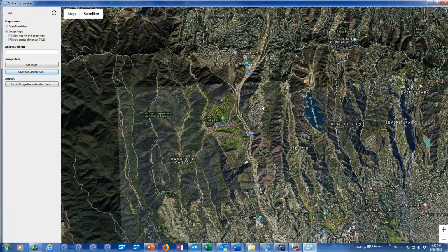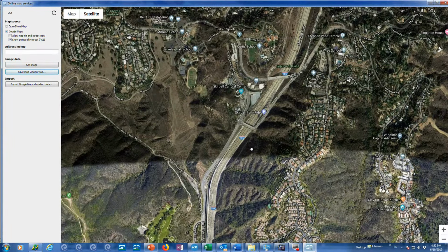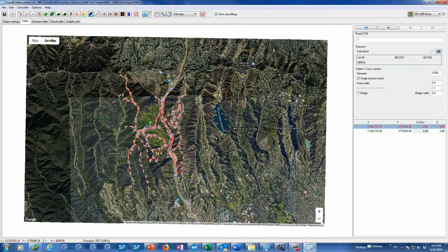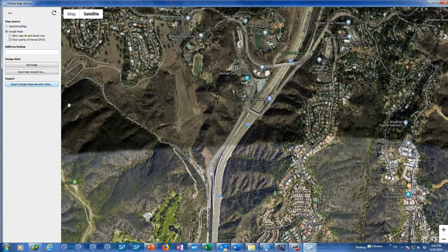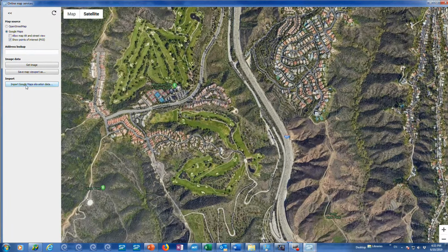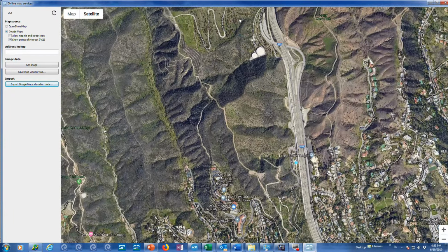And so next step, we go back in the OSM, and so we have that second window. I zoom in right in here, and I import the Google Maps elevation data, and it imports it, it filters it, and it triangulates it. So I move that a little bit further up. I'll do another import. So here you can see what it does, and I'll do a third import.